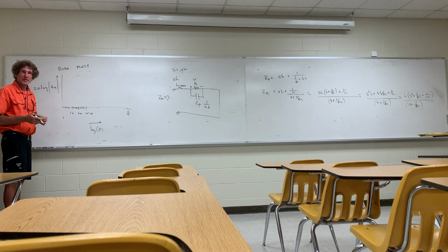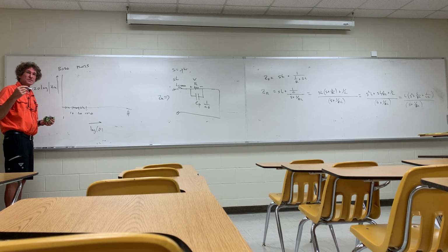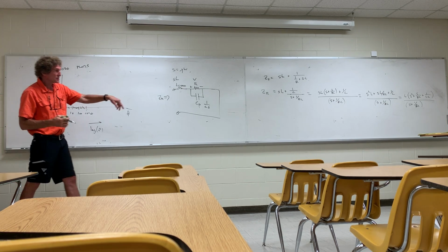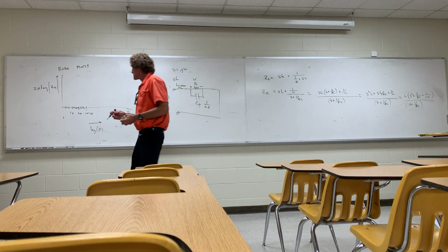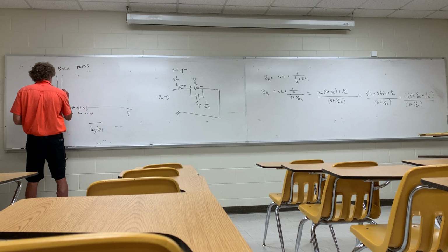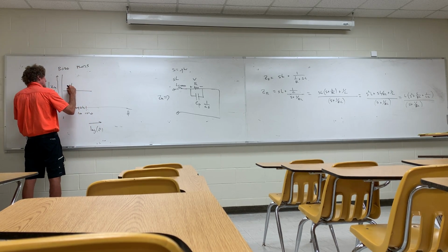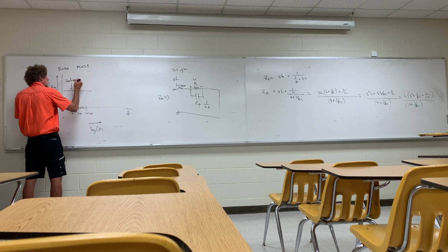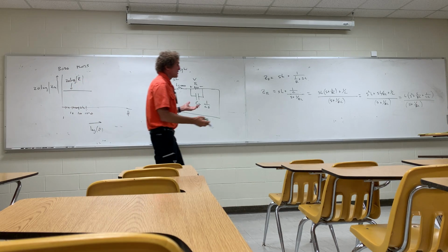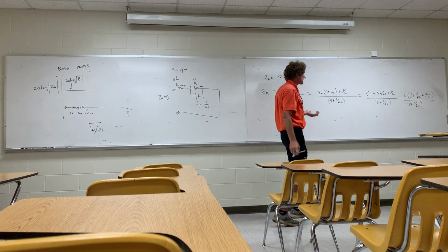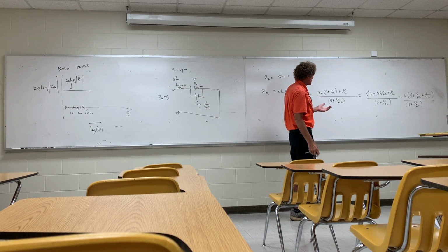Y'all follow me? So when you have a resistance, any resistance, and you plot this right there, here's what happens. At low frequencies, it looks like just the resistance. So this value will be 20 times the log of just R. You can forget everything else, because look, if you take a look at this equation, when S goes to 0, what do you really have?